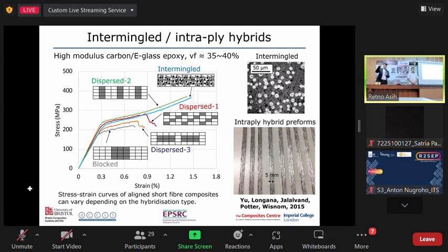For example, a 2 millimeter defect is causing a 10% reduction in the strength of the material. It means that in the longer run, fatigue failure will happen like 10,000 cycles earlier, so we need to do something earlier than what we designed for. So it's more about the application and how you want to use that system for your purpose.